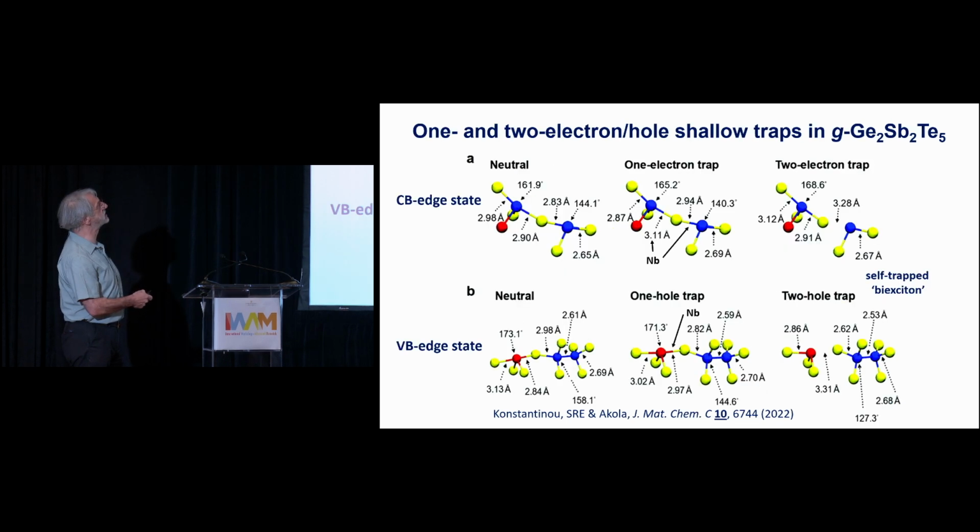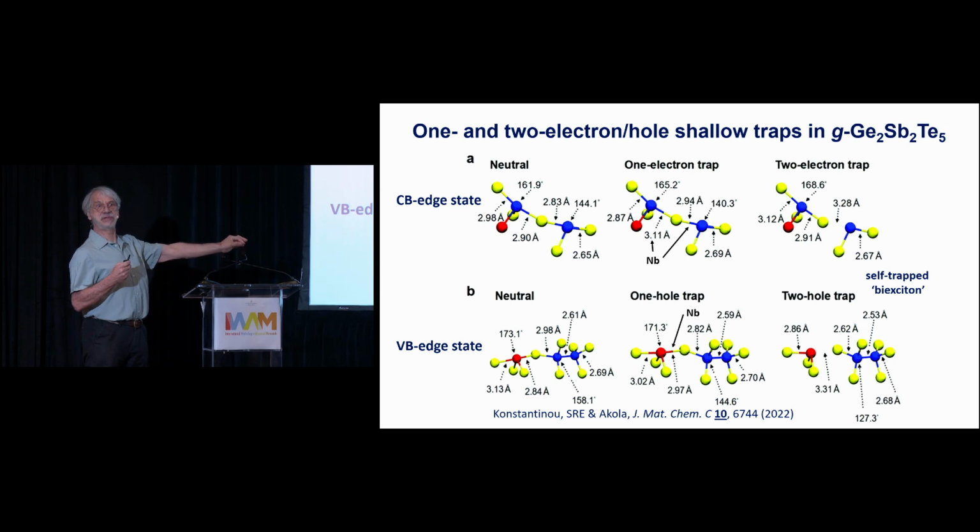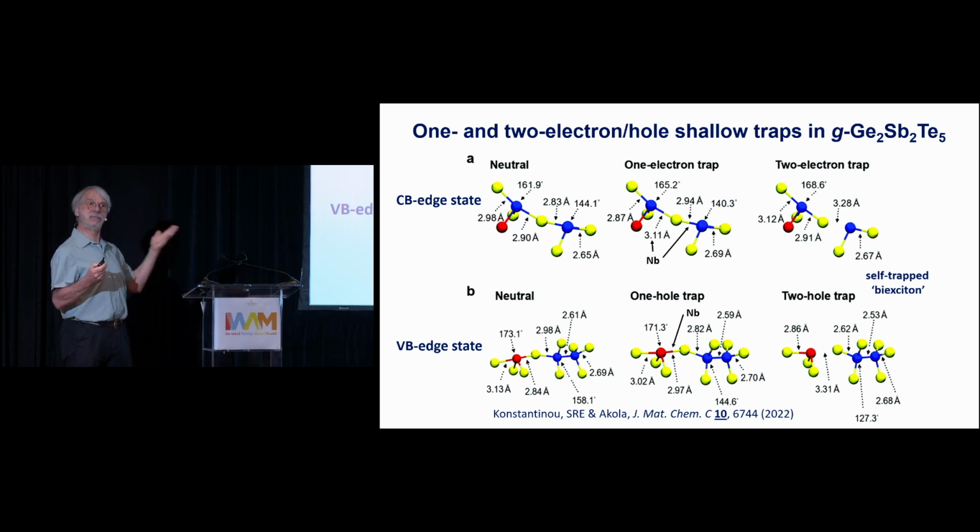Well, because when you do the transformation from a crystal to a glass or vice versa, you apply a very high voltage, only 1 volt, but it's over maybe 10, 20 nanometers, so exceedingly high field for a very short time, and you pump loads of electrons and holes into the system, and it heats up, of course, but the electrons and holes can be themselves trapped. And this is how they can be trapped.